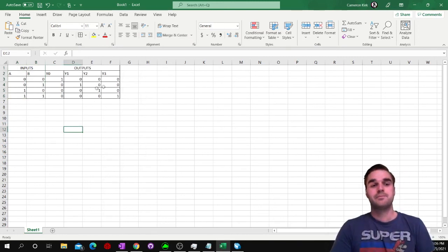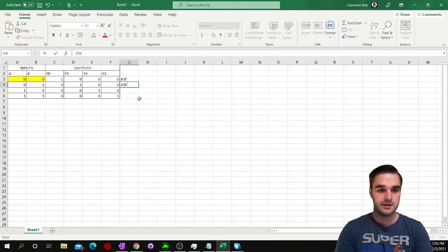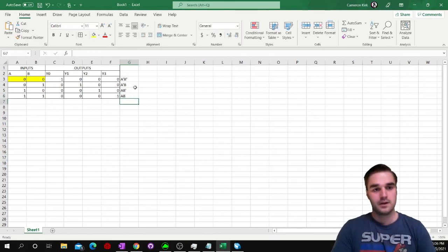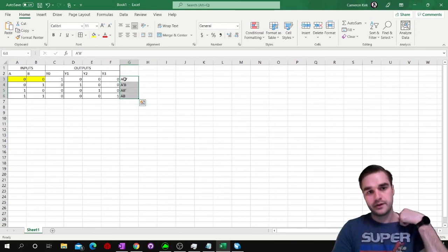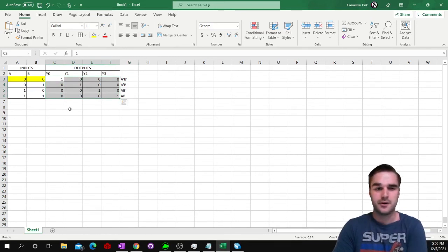Okay, so this equation here can be thought of as A naught, B naught. All right, and then this is A naught, B, and this is A, B naught, and this is A, B. So if you recall from our last video, you'll notice these are minterms. It's just things that are going to be ANDed together. All right, and what we're doing is that we're encoding those minterms. And that's going to be a decoder.